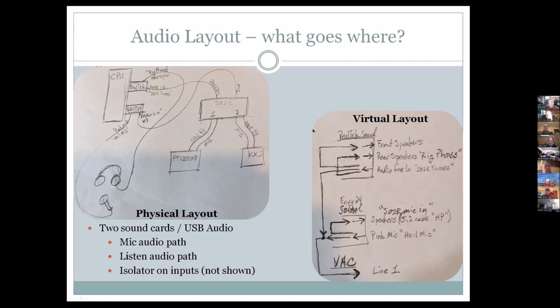There are a couple things with it that I'll talk about in a minute, but one of the reasons I use the same sound card for the mic in path and the phones out path, as a separate one, is latency. If you have a pair of separate sound cards, your output is going to come out of that sound card, go into the computer over USB, travel over a PCI bus, and then come out into another sound card.